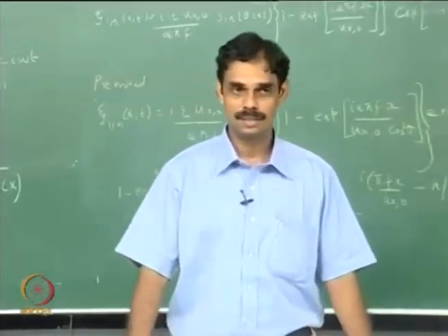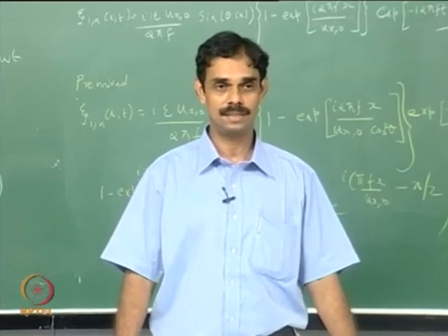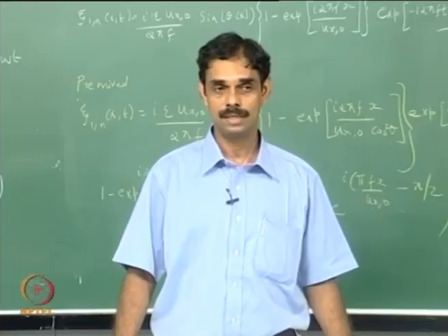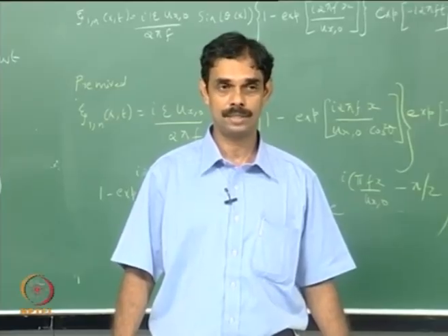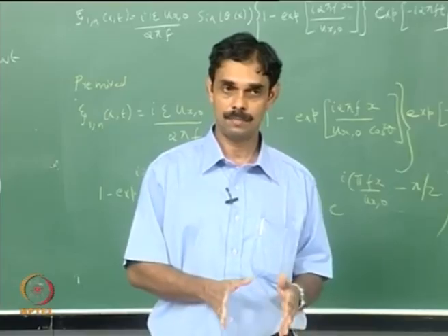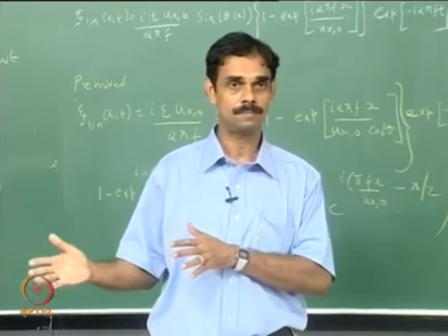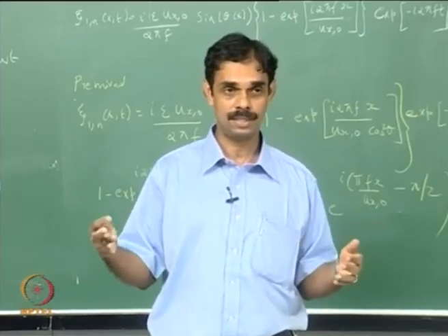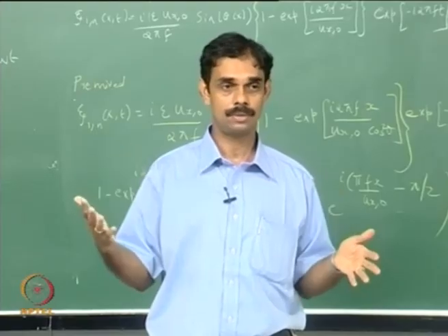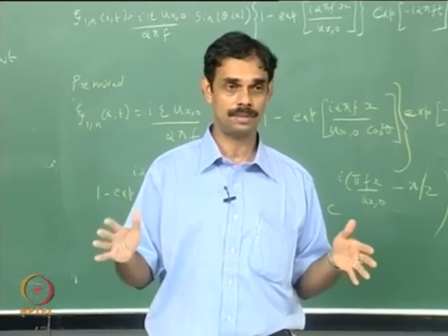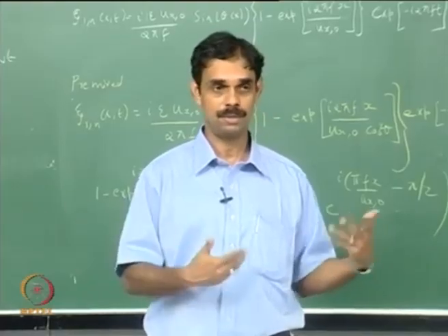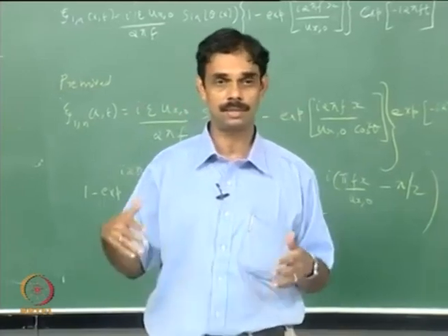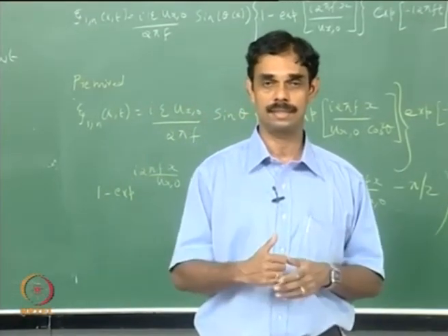Okay, so in the first half of the class we studied acoustics, wave propagation and so on. In the second half we studied thermoacoustic instabilities and we looked at a variety of different situations. We analyzed the problem in the harmonic domain and also in the time domain, and we looked at modal analysis, non-modal stability analysis and so on. The key to all the analysis was the stability part, where you either solve the equation in the time domain or you solve for the growth rates and frequencies, and then we also looked at singular value decomposition, which characterizes energy growth and so on.